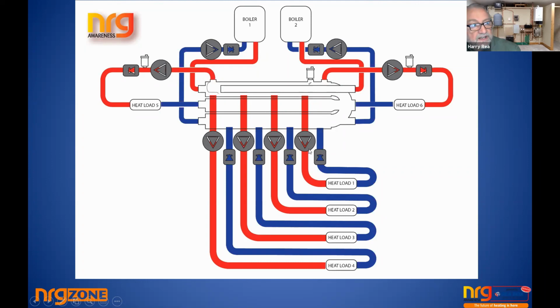There's one other thing I want to say. This is a pump on a 1-inch pipe. If it's a pump with a flow and return on a 1-inch pipe, there is absolutely no reason why this couldn't be a header with 3 motorized valves, or say with 3 other pumps leaving it. So you could actually have 3 zones here and 2 zones here and 4 zones here, because if 2 1-inch pipes will do a house, there is utterly no reason why you couldn't have multiple zones of those pairs of connections. But of course, back to the rule again, you can't take out more than what you put in. So if all your zones add up to a certain amount of water activity, you must introduce that water in from the boilers. If it doesn't, the zones can't work.